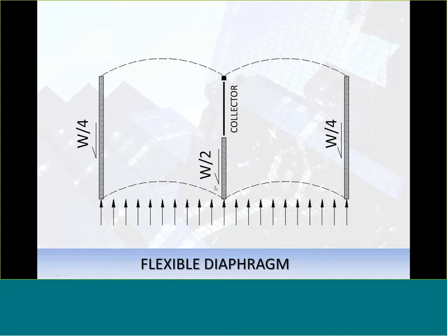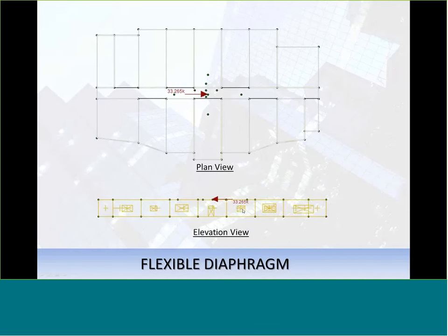Those are going to see the uniform load divided by 2, or half of that uniform load, and then we're going to see a quarter of the uniform load again on the outsides. So still based on the tributary area. We're going to find how much tributary area there is, considering that the collector is there to take the load as well. This would be considered a lateral element, so it's there to collect it as well. So we can see it a little bit more.